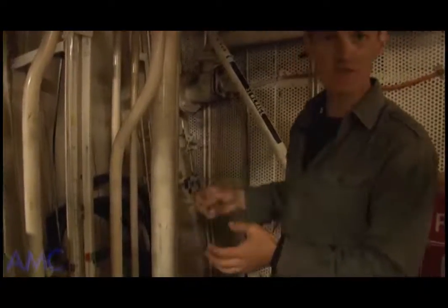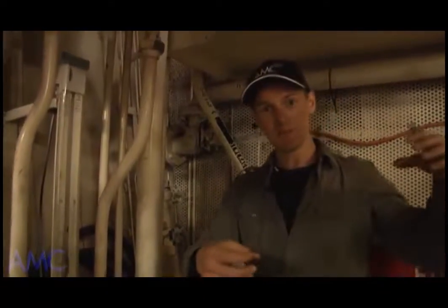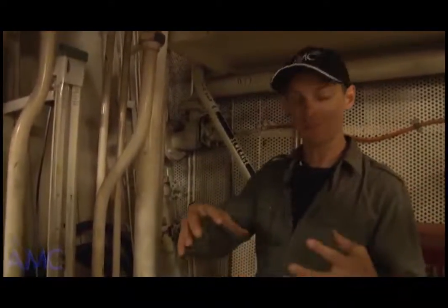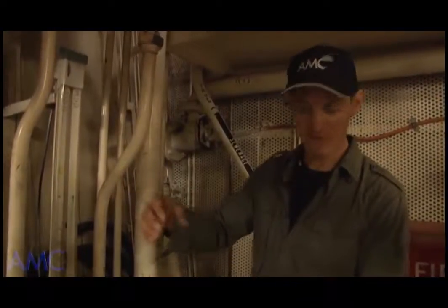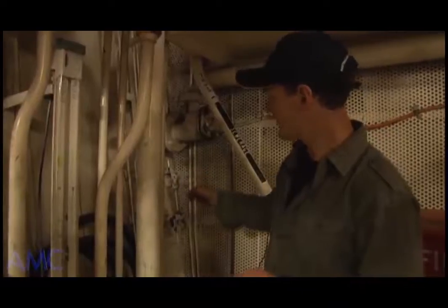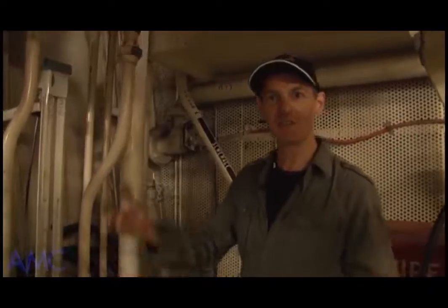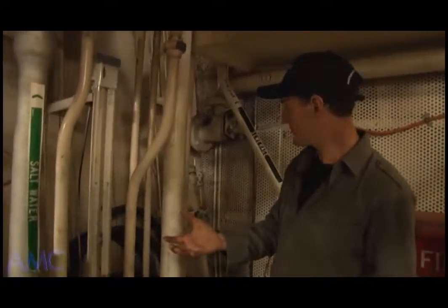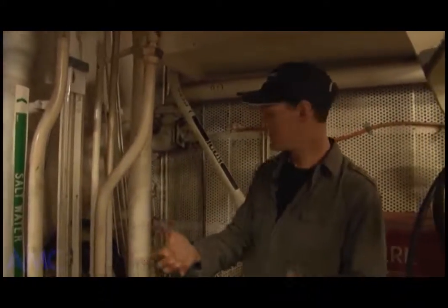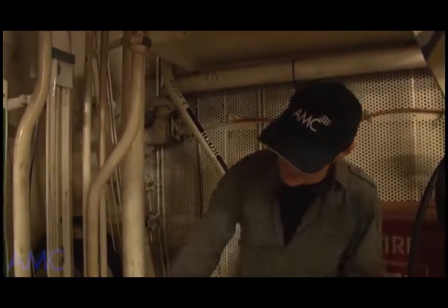We go to a purge cycle, and what that's doing is allowing the fuel to come in and work against the air pressure that we've just applied to it. We go to another position called wait, give it 10 seconds and it just lets the system calibrate, and then we can go to the read part of the cycle, which I'll switch over now, and we should see our level come up, and this is going to correspond to the level that's in the tank that we're reading.